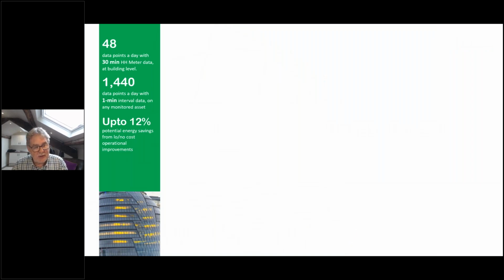So in terms of data, there's various levels of monitoring and metering out there, and a lot of sites will have half-hourly meters fitted, so there's 48 data points a day available to assess some form of energy use, and that's a kilowatt hour level. That's useful for maybe looking at base load management, what's happening on site, out of hours, weekends, etc.